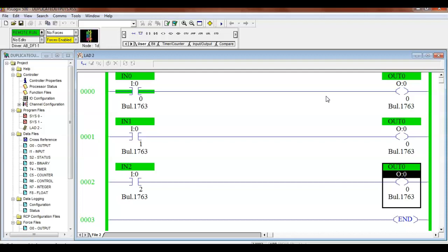Why did it go true? Because this is telling it to go false, and this is telling it to go false. And the way the thing scans, it scans here, it scans here, it scans here, and then when it updates the output, this guy right here, the last one, is telling it to do what? Turn off. So I'm going to flip the next one. Okay? It still don't go through. Y'all see what I'm saying? Now let's switch the last one. Now all of them go through.